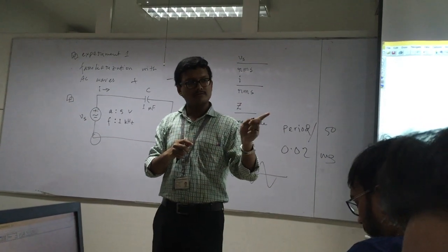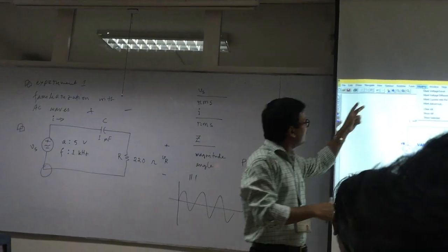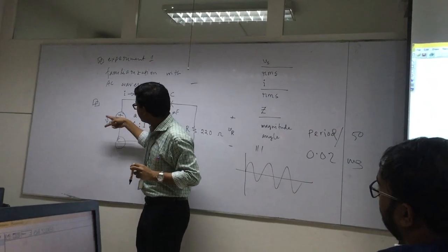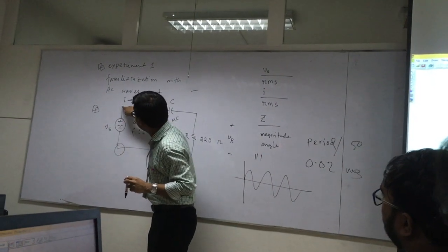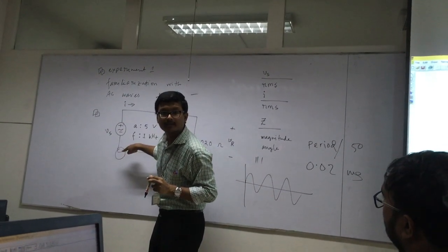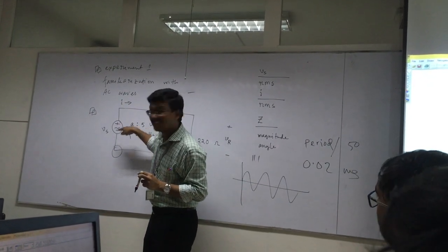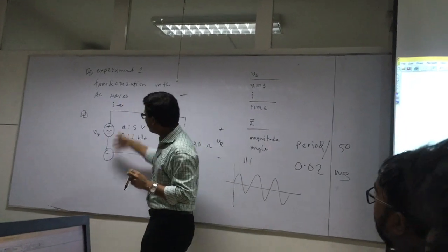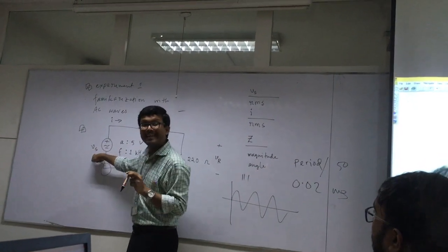Nodal voltage needs a ground. For example, if I say nodal voltage of this node, what do I mean? Okay, voltage of this node with respect to ground is the nodal voltage of that node. Okay? So you need to understand. Now, which one is our target? This guy. We can select it. I mean, look at this, plus minus. So if I say this is the voltage of this node with respect to ground, am I correct? Definitely I'm correct. Because voltage of this node gets the plus, with respect to gets the minus. Okay? So according to the definition, this nodal voltage is the same as Vs, which we need.